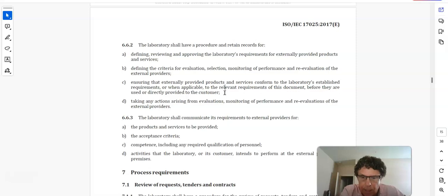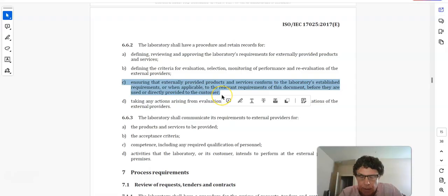You didn't buy the ISO 17034 produced weights, even though Tromner is ISO 17034 accredited. You have to specifically tell the vendor what you want. If that was the case and you bought the wrong weight set, then you violated section 6.6.2, section C of the standard.